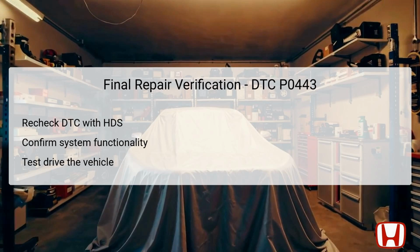After confirming no faults are present, take the vehicle for a test drive under various operational conditions to gauge performance. Observing smooth operation without any check engine light activation during the drive further substantiates the success of the repairs done to the EVAP system.